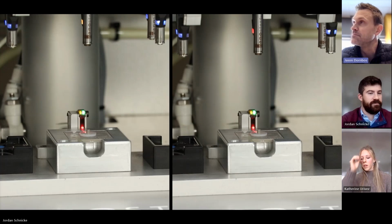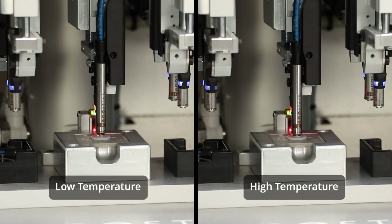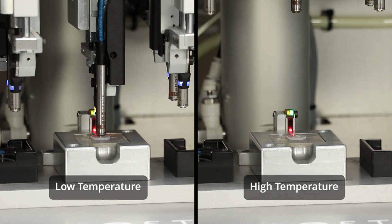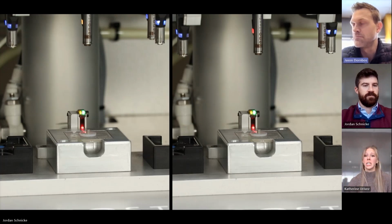If you want to play that video again, between these two cycles, they are the same dwell time and they're the same cool temperature. The only thing that's different between them is the one on the left is at more like 500 degrees. The one on the right is more at like 650. So just to show you that you can shave a little bit of time off your cycle just by changing the heat temp alone.